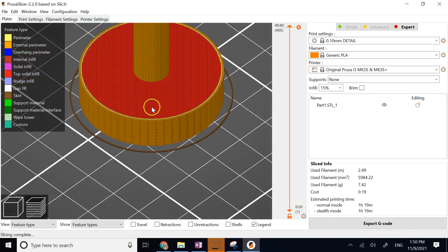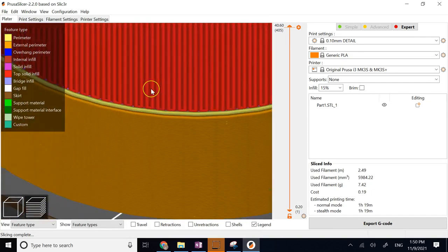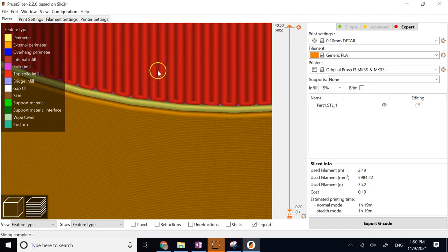But now if you look at the flat surface, like this surface in red, you clearly see the difference. So this surface here in red is a flat surface, only X and Y motion. And you clearly see the thickness of the plastic coming out is way bigger than the layer height. So it's like 0.4 mm, while this guy here is just 0.1 mm. So in this picture, you can see very well next to each other the nozzle diameter or the XY resolution versus the Z resolution.